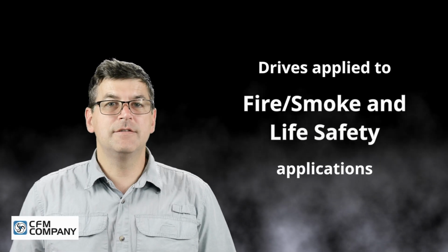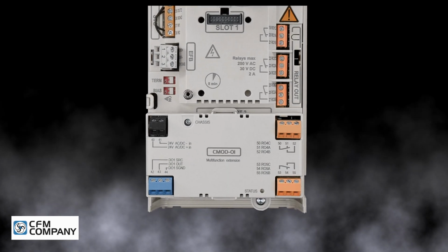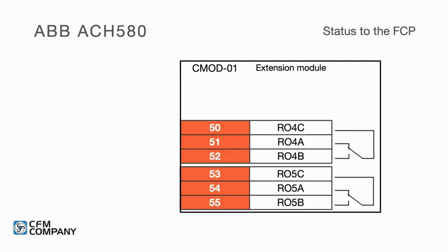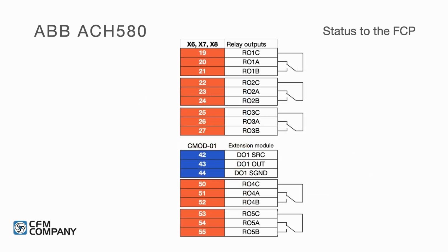As a standard for drives applied to fire, smoke, and life safety applications, CFM Company includes the optional extension card CMOD-01. This card adds 2 additional Form C relay outputs, RO4 and RO5, and 1 digital output, DO1. At startup, CFM Company will program the relay outputs to indicate a locked rotor, a broken belt, motor run status, and a VFD fault. In addition, if needed, a relay output is available to control a damper actuator.